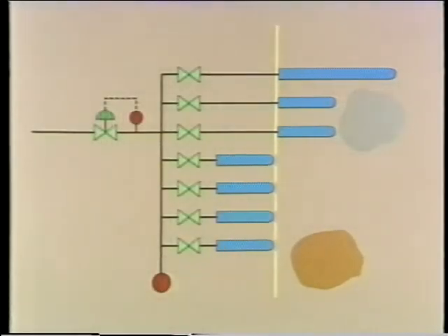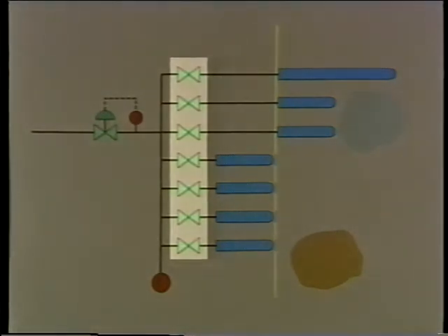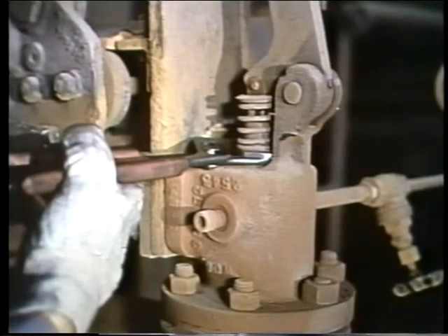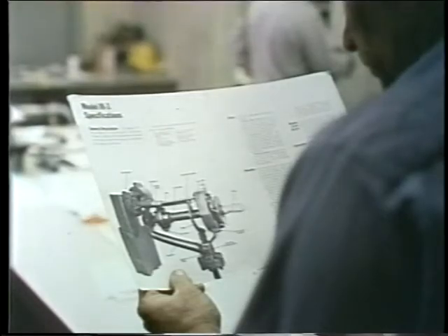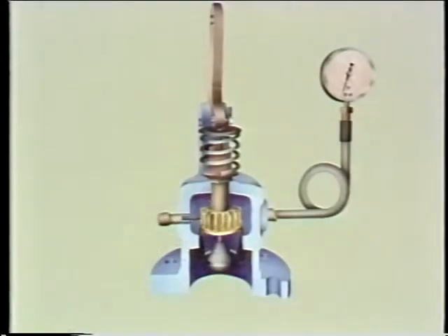Pressure to the soot blower could also be regulated by the soot blower's valve. Assuming system pressure is high enough and no leaks are present somewhere else to cause a problem, the valve on soot blowers, like these and many others, can be adjusted individually. Your shop office will have specs for each blower in use at your facility, and the manufacturer's manual for each type will give you details of how to make these adjustments. Generally, though, the adjustment can be made fairly easily.